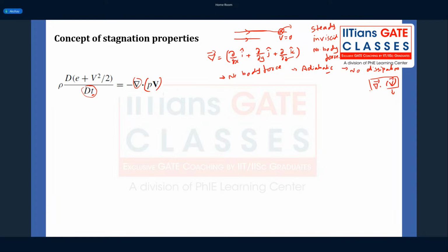In general, you can apply it to higher dimensional tensors also, like a second order tensor such as a stress tensor. When you apply a divergence on a stress tensor, you get a vector. When you apply a divergence on a vector, you get a scalar. That is how the order reduces. Whereas when you apply a gradient operator on a scalar like rho, the order increases: the scalar becomes a vector, and the vector becomes a second order tensor. The curl operator, when applied on a vector, stays a vector, so the order does not change. These are the properties of these vector operators you should know from your basic mathematics courses.